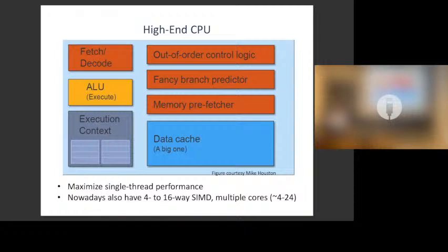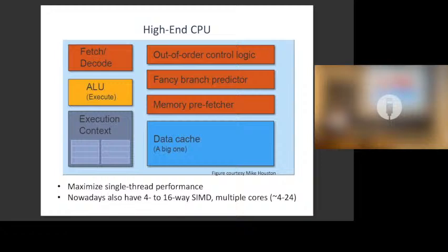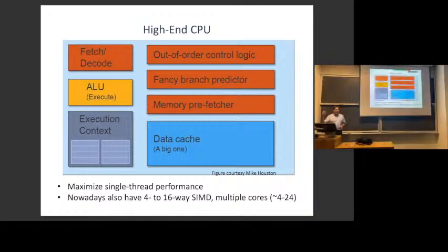And the prefetcher basically watches the pattern of addresses that you're loading and guesses what data you might want next. And before you ever ask for it, it's already put it in the cache. So that, again, you don't stall the program. Main memory takes maybe 30 nanoseconds, 50 nanoseconds, depending on the type of memory, to access. And a processor has a clock period, if it's a high-end processor, of maybe 300 picoseconds. So you're talking 100, 200 cycles typically to get data back from main memory.